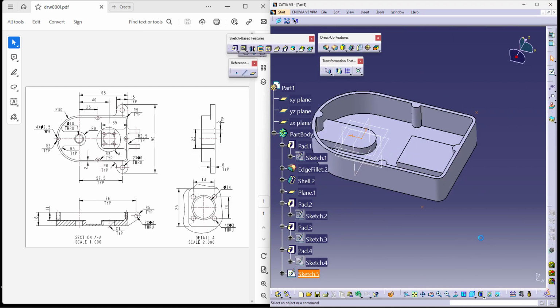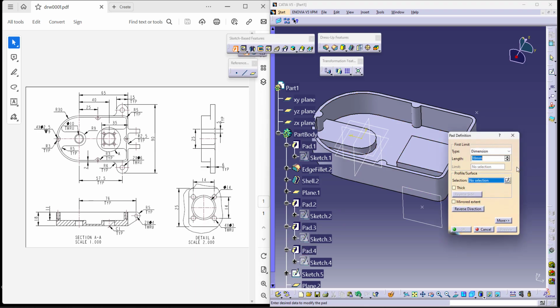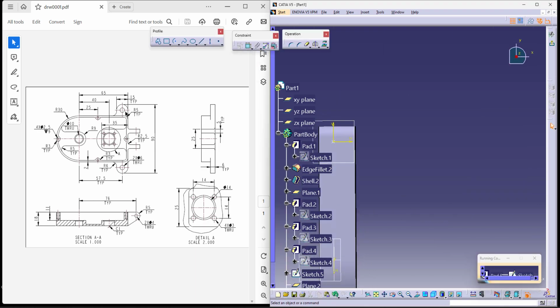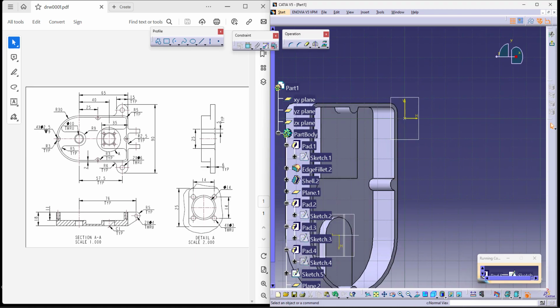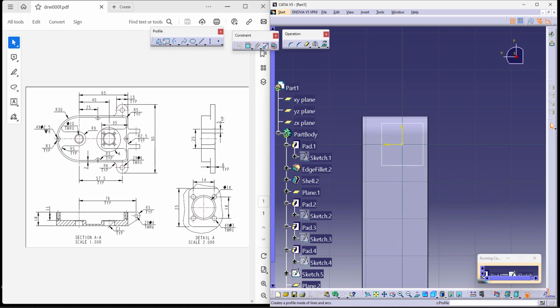90 is to the end. So since 90 is to the end, when I take a plane, making it parallel through a particular point, it can automatically take the addition of material properly. I have not given a center to center dimension anywhere. Now, over here, the addition of material actually begins in the form of a rectangle from the corner. I can again start giving constraints, or of course we can use constraints and coincident over here. We know the distances as well. This is supposed to be 15 and the height is supposed to be 6.